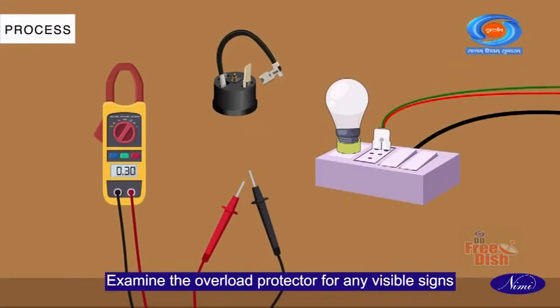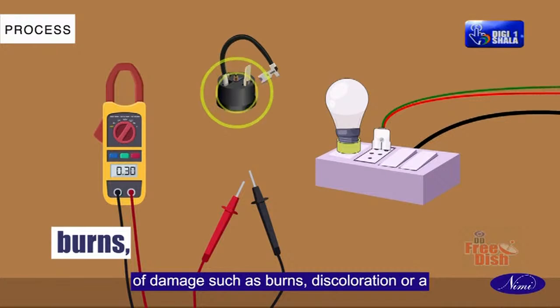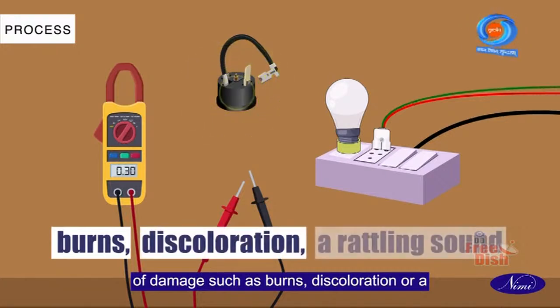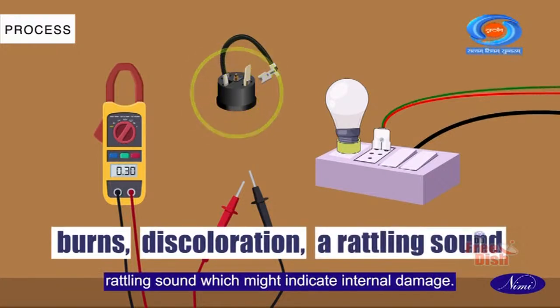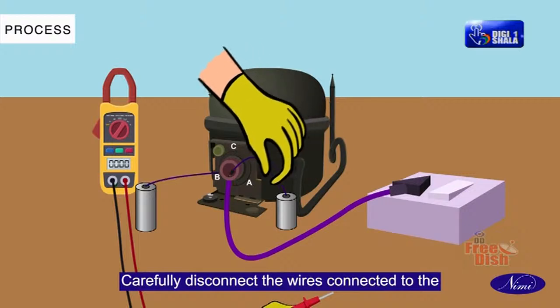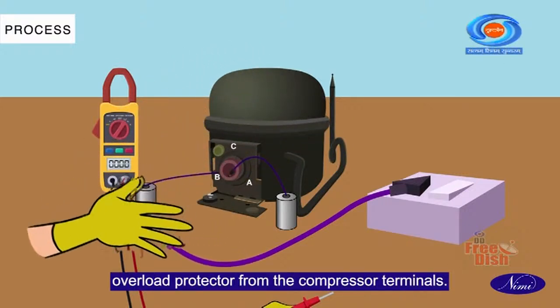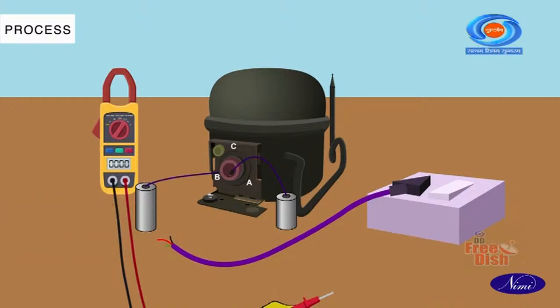Examine the overload protector for any visible signs of damage such as burns, discoloration, or a rattling sound which might indicate internal damage. Carefully disconnect the wires connected to the overload protector from the compressor terminals.